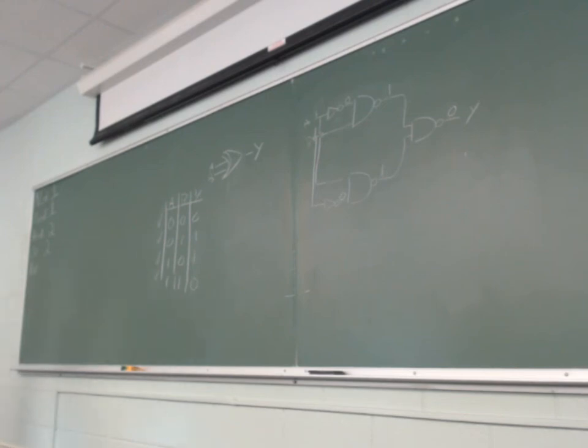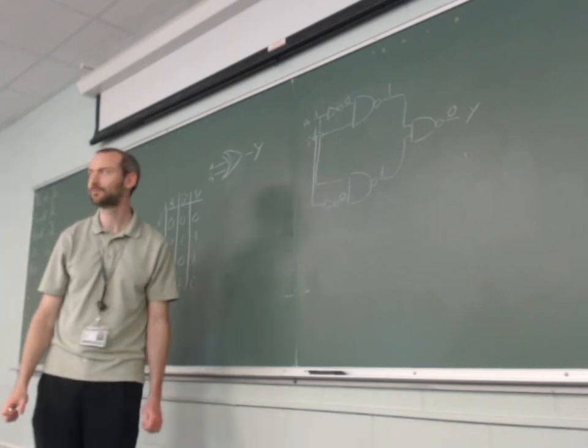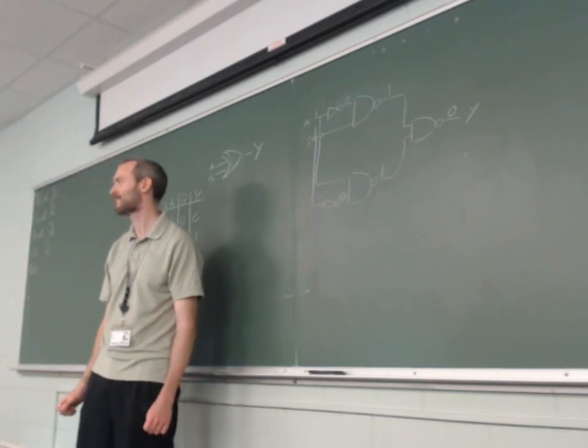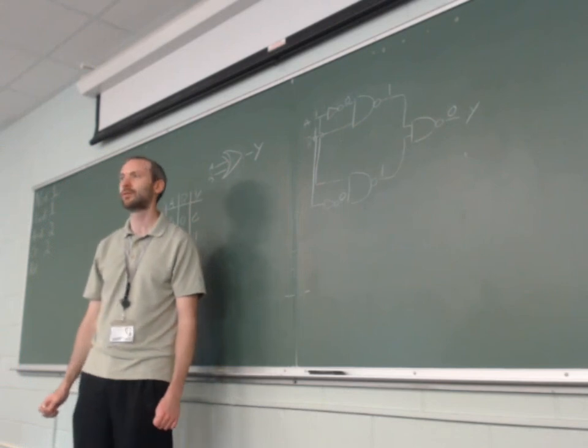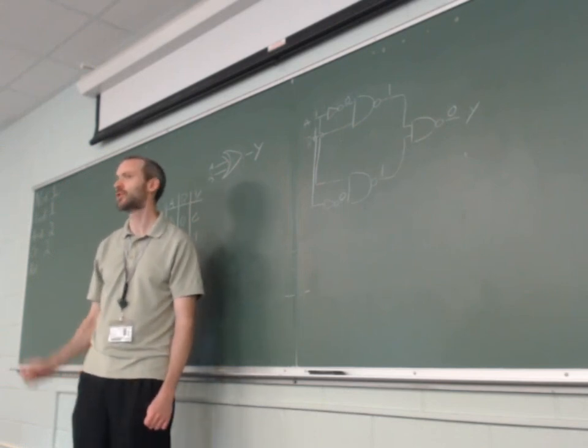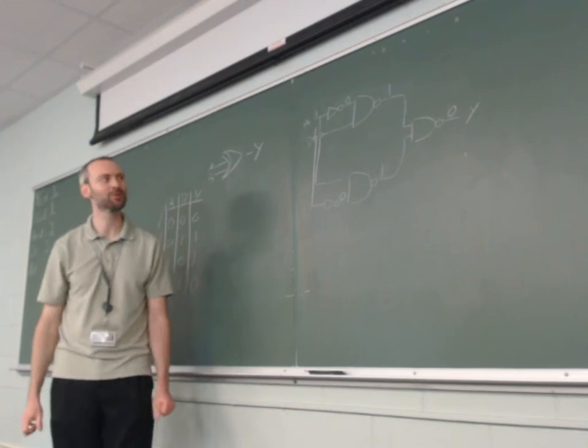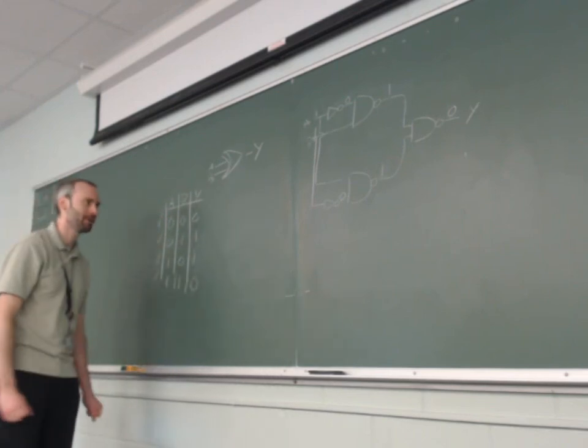What's the gate delay here? 3. Do the NOTs have a parallel? We have 2. And then the two NANDs have a parallel on the last. Each NOT, even though there's only one for each input, is actually waiting for the NOT, so that counts as one going through each. So we're getting different numbers. We got 4, we got 3, we got 2.